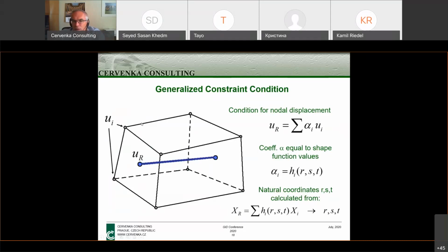Because in typical reinforcement with ribs, the bond failure is nothing else than cracking of the surrounding concrete. So if we have a sufficiently fine mesh, this bond failure can be represented quite well by cracking of surrounding elements. But in addition, in ATENA, we have the possibility to take this bond into account directly.